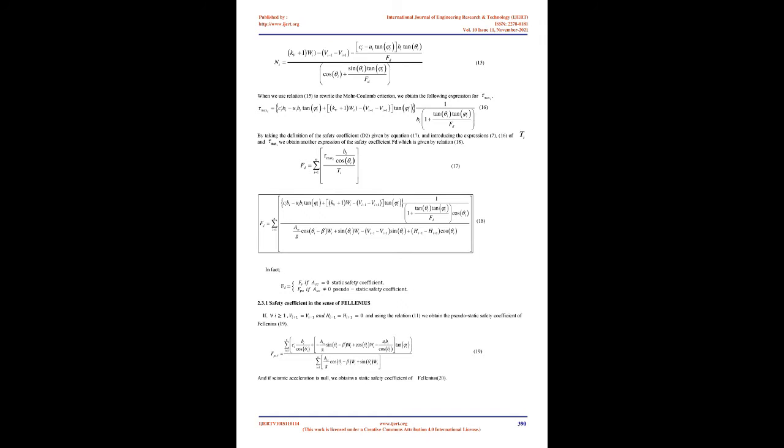The equation of the equilibrium problem of a massif is based on the following assumptions. The soil mass is assumed to be continuous. The studied problem is plane and there are no edge effects. The external forces are the weight of the soil, the surcharges, and possibly the seismic forces. No account is taken of the driving forces that can be created by water flows.